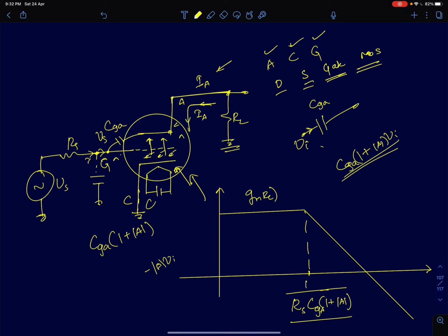Now by applying a voltage on the third terminal, called the grid terminal, we can control the flow of current between the anode and cathode. So IA here can be controlled by an appropriate voltage at the grid terminal. And we said this is like an amplifier operation. In any 3-terminal amplifying device, we can control the flow of carriers between 2 terminals by application of a voltage on the third terminal.